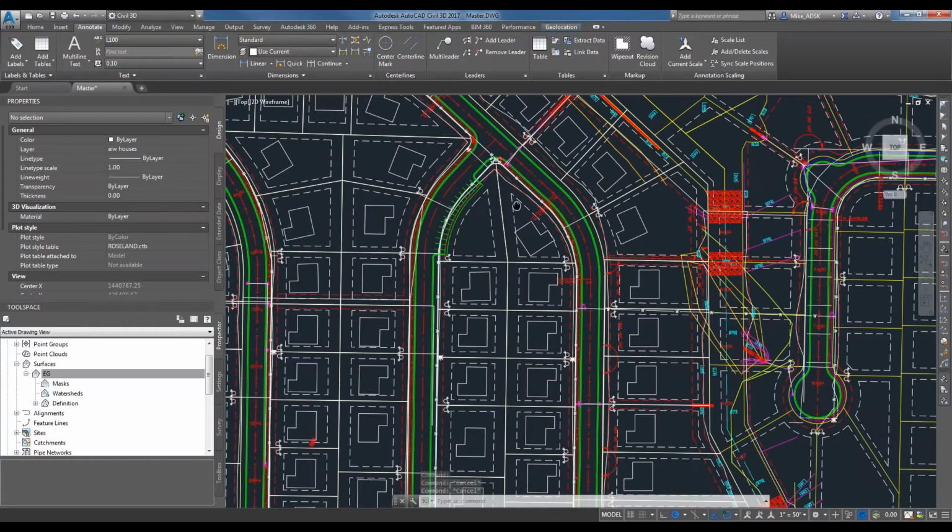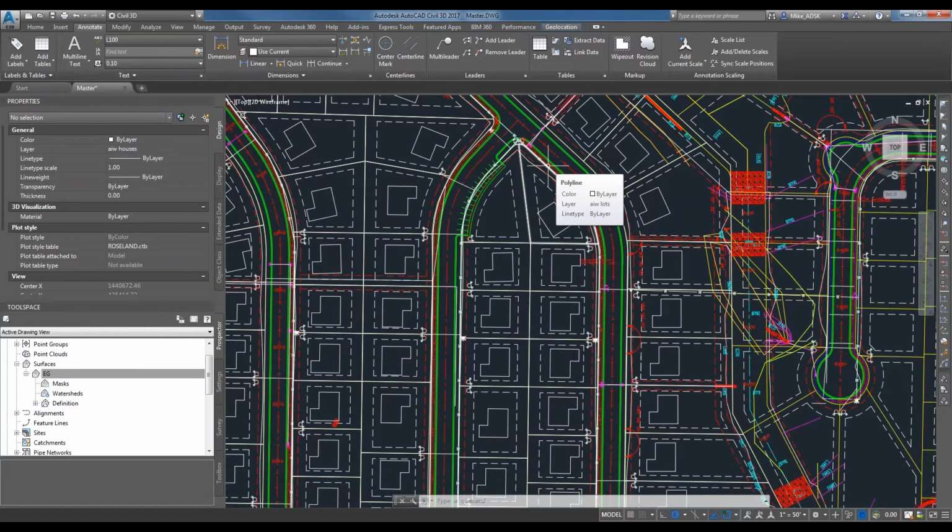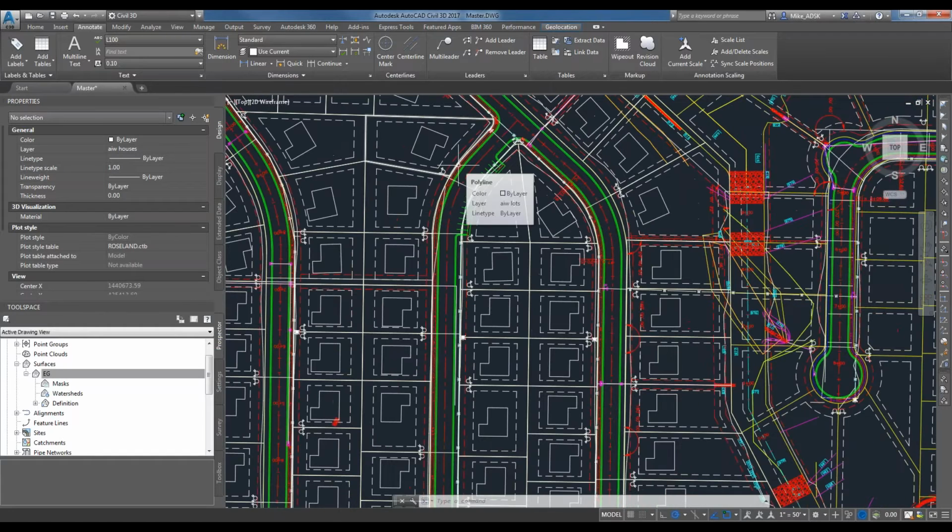So the cool thing about Civil 3D is that you could make corridors. You hear corridors and, well, what are they? It's your roadway. That's really what the corridor is. It's kind of split up into 3 separate sections. You have your horizontal design, you have your vertical design, and then you have your cross sections. So right now I'm going to start off with the horizontal design. Horizontal design is what's called your alignment. Alignment can best be thought of as your center line. So if you're ever driving down a street and you have your double yellow line, you can think of that as your alignment.